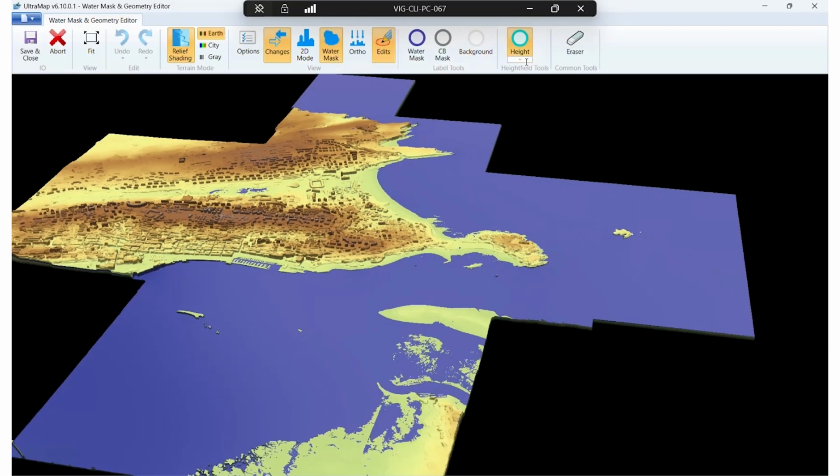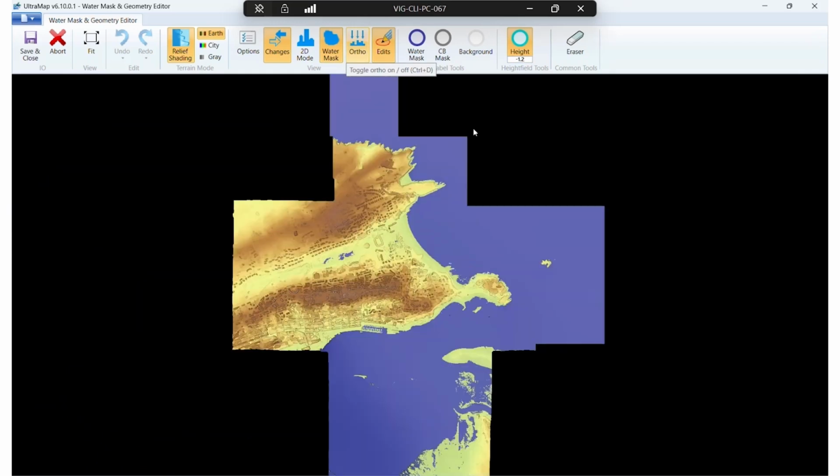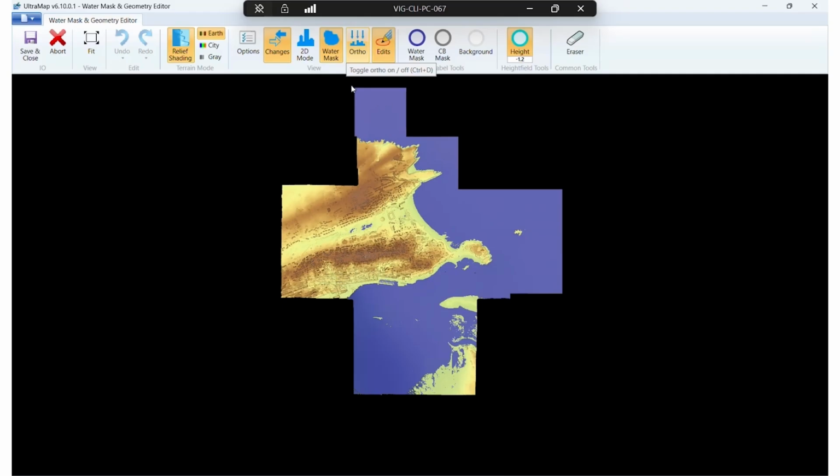And with this tool here, this value of 1.2 meter, which should be used for the water body, can be entered, and then the tool can be used to create a polygon, and all the water within this data set gets now this new value for the height of the water.